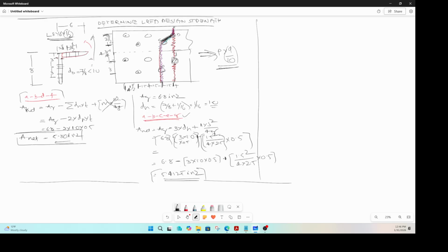So you compare this load with this net area, and use that load and this net area in your calculations. Or if you want to treat everything fair, you come back and increase this net area by a factor of 10 by 9, and then use that to compare with all other paths and pick up the minimum value.